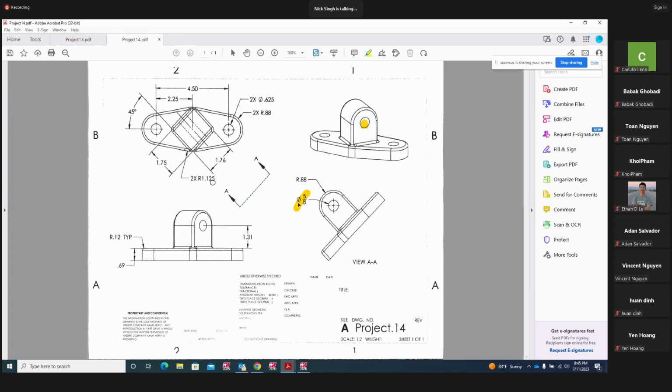So create that radius, which is, like I said, 1.275, not 1.125. Make a note on that. I'm going to go to arc polar in the top plane, draw these two arcs, and draw these two circles, which is radius 0.88. And then we're going to create these two arc polar, and join this with the tangent line. Okay, so let's draw this 1.275 arc right here. Again, make a note, this is 1.275, not 1.125.